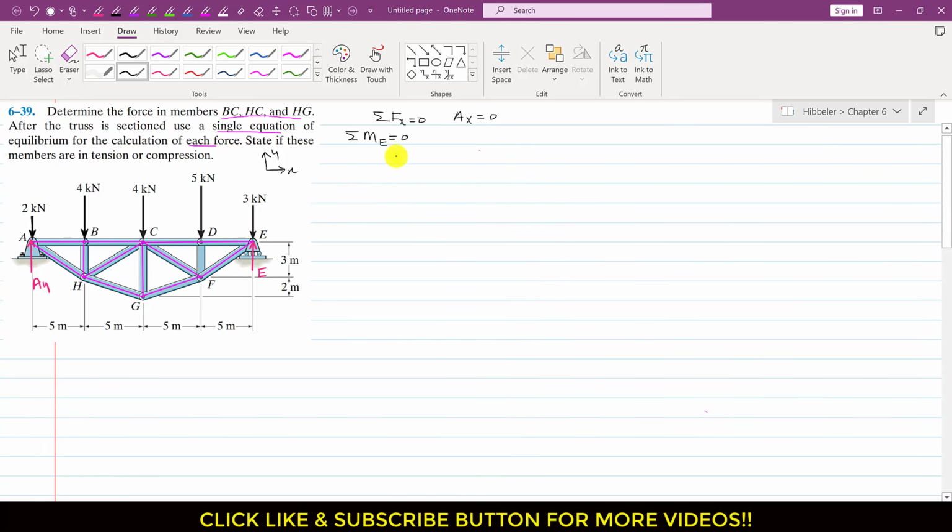Now if I apply the summation of moments about point E equals 0, as we can see, this AY is producing a clockwise moment about point E. So I will write minus AY, and the moment arm of this AY from point E is the summation of all these lengths, right? So this is 5 plus 5 plus 5, so this is 20. I will multiply this with 20.